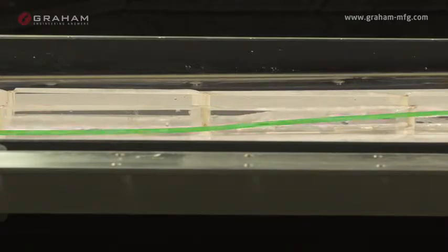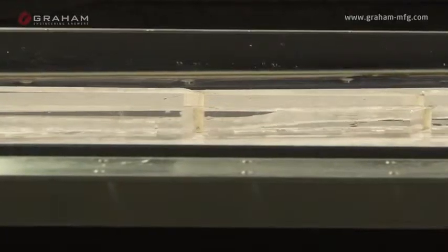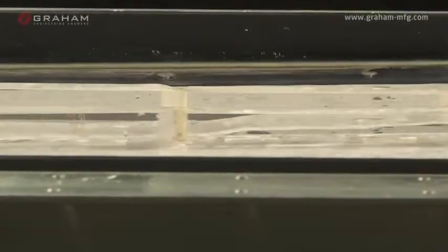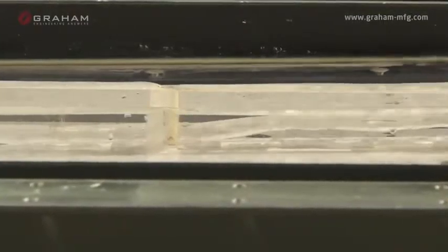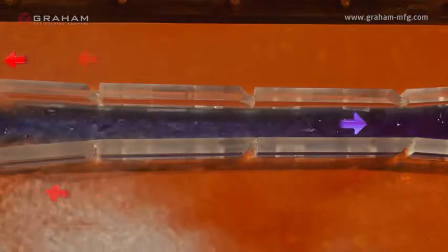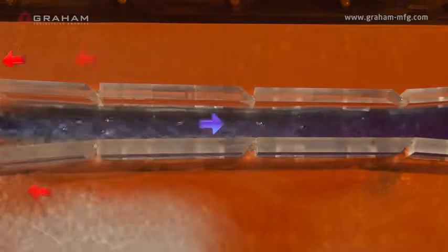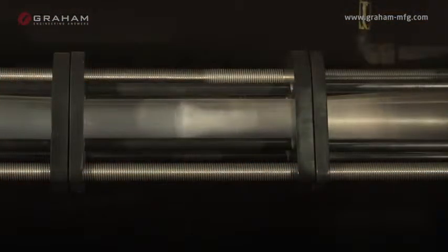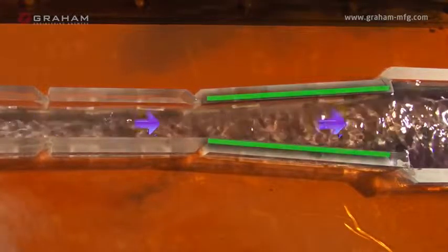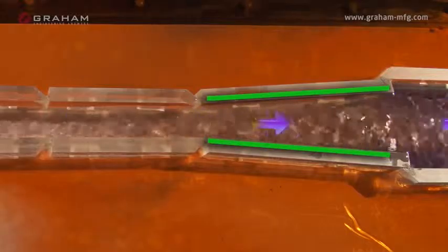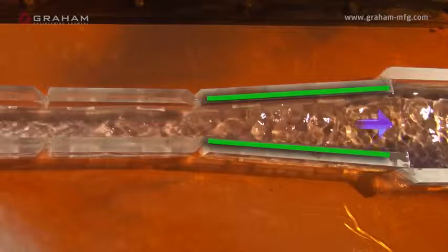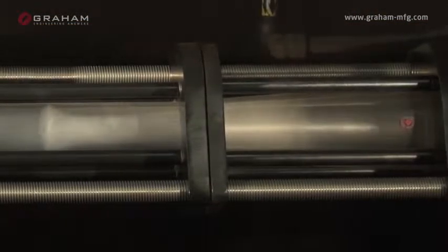Through the throat, there is a step change in pressure, temperature, and velocity across the shock wave. Pressure and temperature increase while velocity drops below sonic, which can be seen here as a sharp increase in height. In many cases, one can feel the temperature difference across the shock wave. More than 50% of the ejector's compression is done across this shock wave, which is why it is so important to the ejector's operation. The outlet diffuser is diverging and contains subsonic flow. This continues to slow the velocity of the flow by increasing cross-sectional area and increases the pressure up to the final discharge pressure. These same principles are seen in a well-performing ejector.